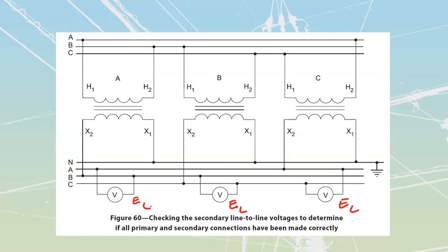As soon as you get something that isn't reading proper line voltage, that means that you've got that nasty little chicken's foot. We saw that one in one of our earlier videos, where if you flip one of these around, this one should be up over there for a Y type of system, but if you connect it incorrectly, you end up with this chicken foot, and you end up with these weird little voltages that are going to be inside of it.